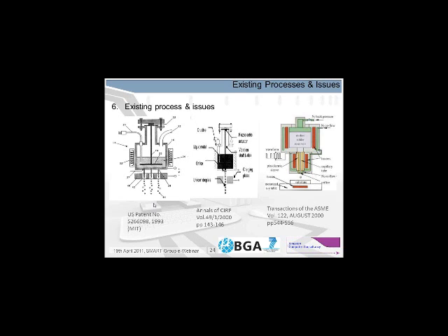A key feature you can see is this upside-down dark T, which is your transducer, producing a pulse, almost pushing the solder balls out through multiple nozzles. It's a high production system that was designed to make a large number of micro solder balls.